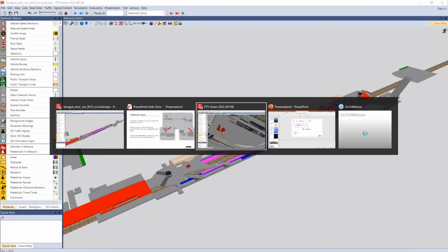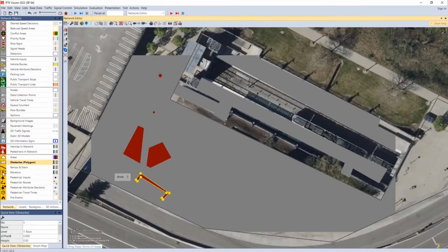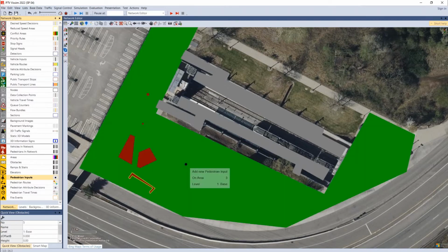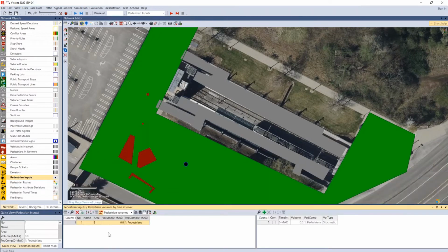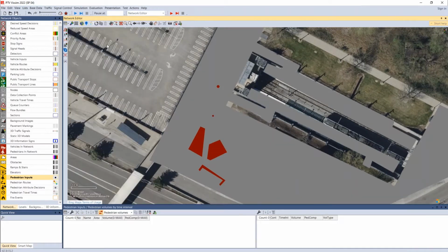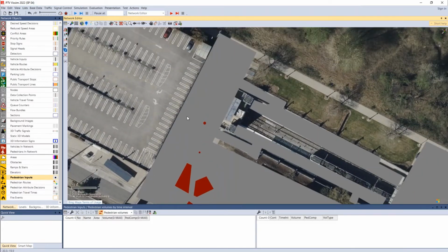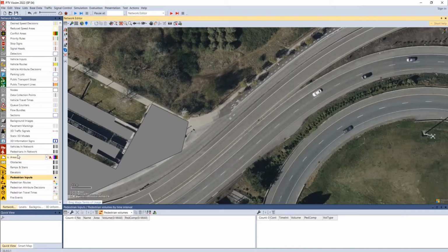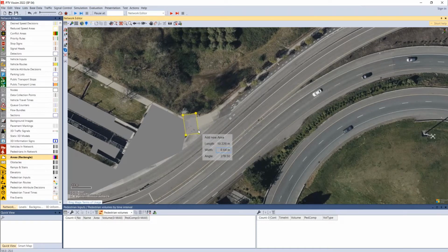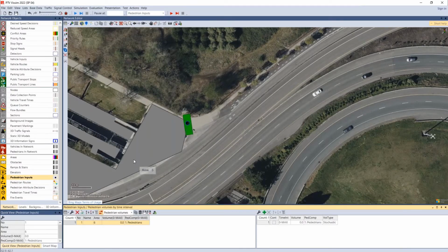So in our model that we're building out, we might place a pedestrian input on this larger space to generate pedestrians. That is totally okay. I just hold control and right click, and now this larger space starts generating pedestrians. But a more common way to do it is to look at where are the actual access points to the network. So for example, we might create a dummy area towards this end because we have this sidewalk that people might be walking up to the station from. So I'll create a quick dummy area there, and I might put a pedestrian input on that space.